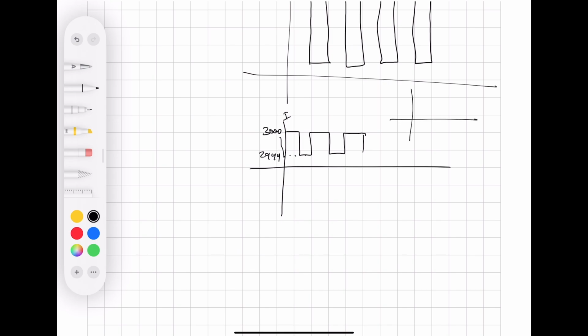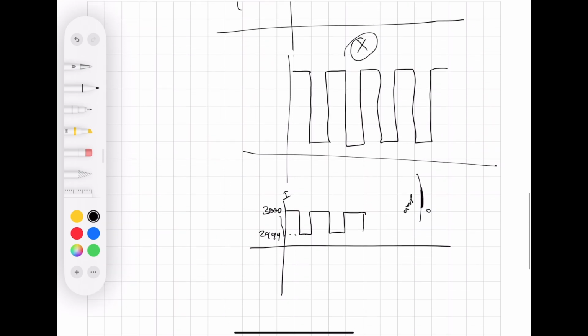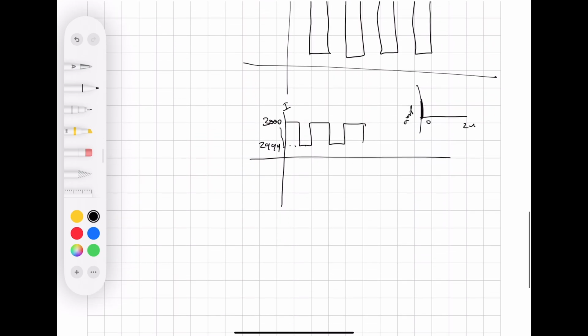What that has to do with is, let's say that's your frequency in hertz, or to simplify this, amplitude. What a lock-in amplifier does after it mixes is it's going to have a signal at the subtraction of the frequencies of the two waves, and at twice the frequency. So what a low-pass filter does is it actually filters out.